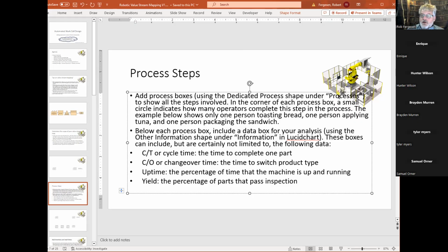So the ideal automated work cell should be flexible across the whole range of products for a given product line. And so you might have some changeover to move from one style product to the other. Ideally, if you can, you set up your fixtures and your grippers so that you don't have any changeover requirements. You can instantly move from one product type to another. But practically speaking, that's not always true depending on the business.